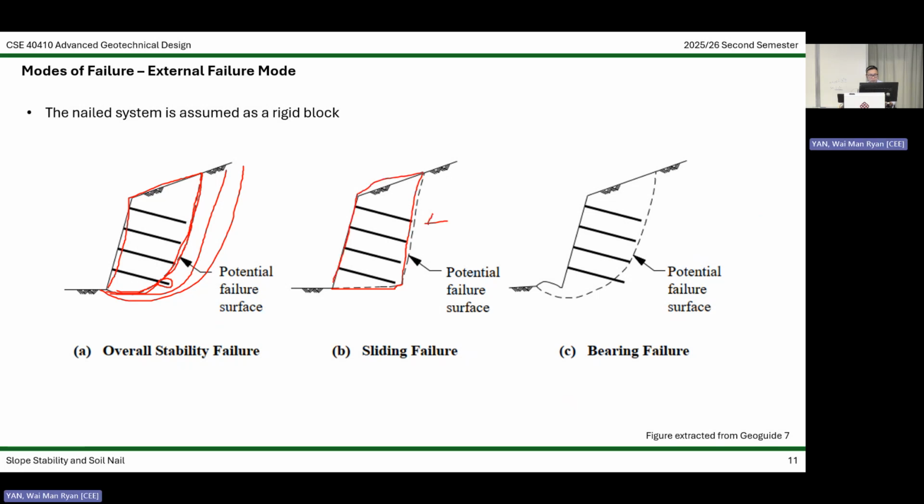So you have pressure pushing here, you have friction, and then you consider whether this friction is sufficient to hold that lateral pressure, active pressure basically, with a sufficient factor of safety. And bearing capacity failure, same thing. The whole thing works like a block, and then whether you have this failure thing, right? Bearing capacity failure. So not much different from a retaining or gravity wall. Okay.